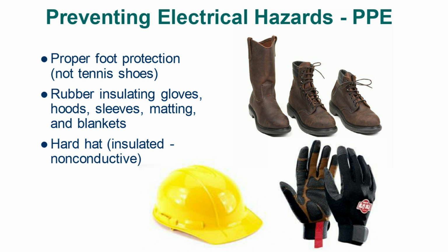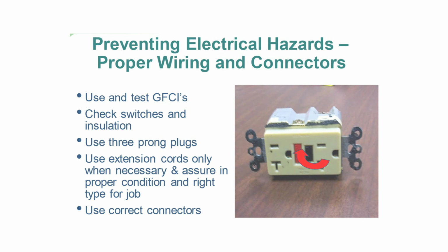Preventing electrical hazards, PPE: proper foot protection, not tennis shoes. Rubber insulating gloves, hoods, sleeves, matting, and blankets, and a hard hat that is insulated and non-conductive.